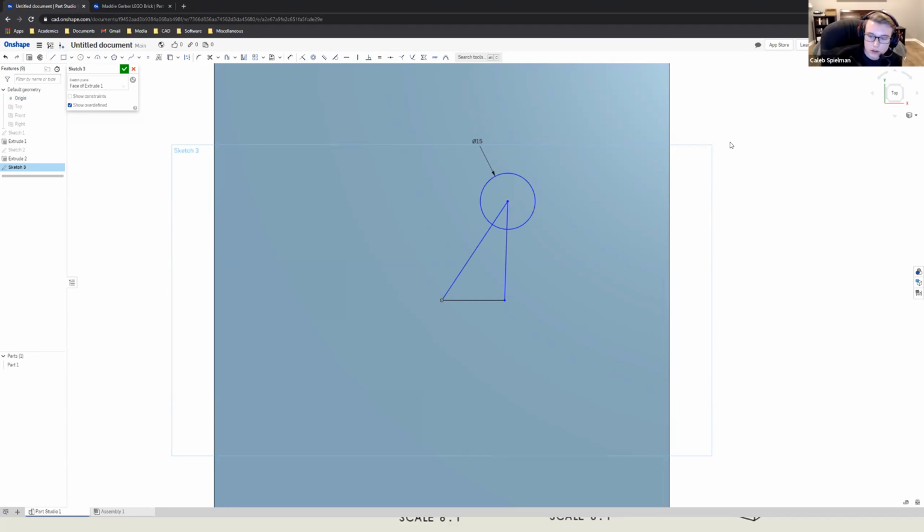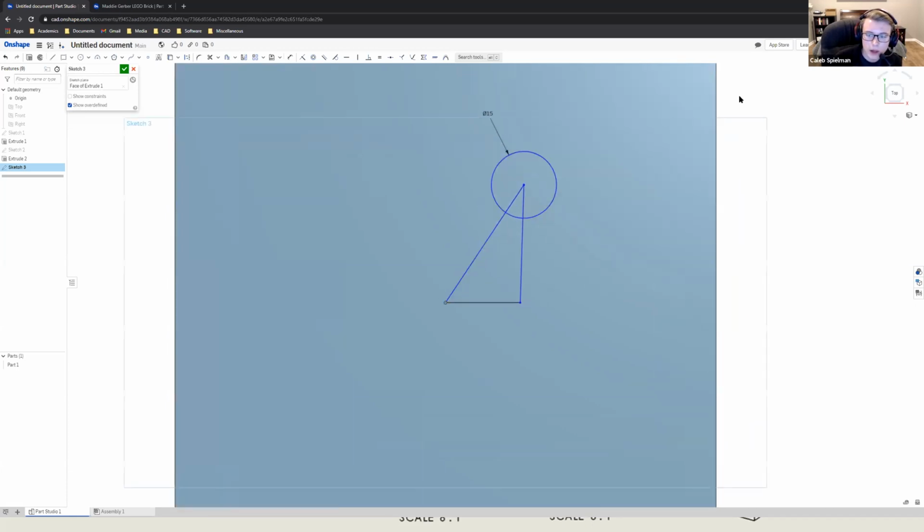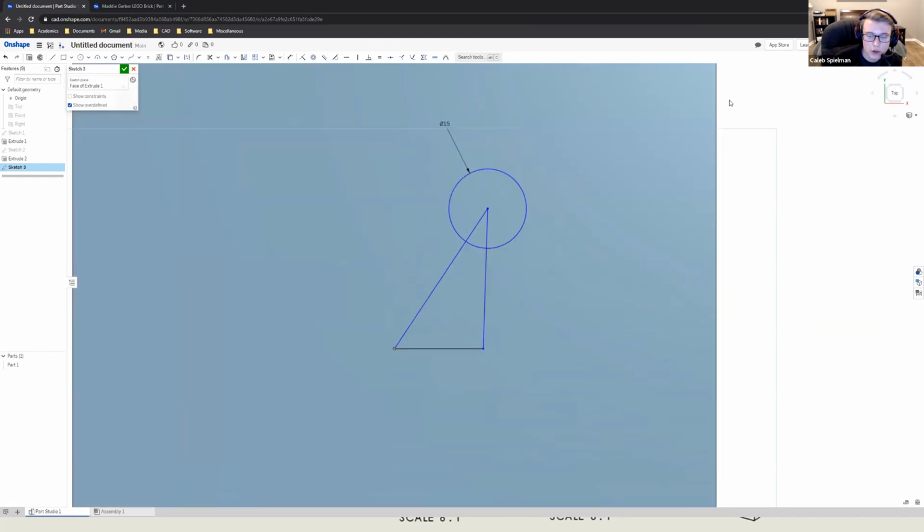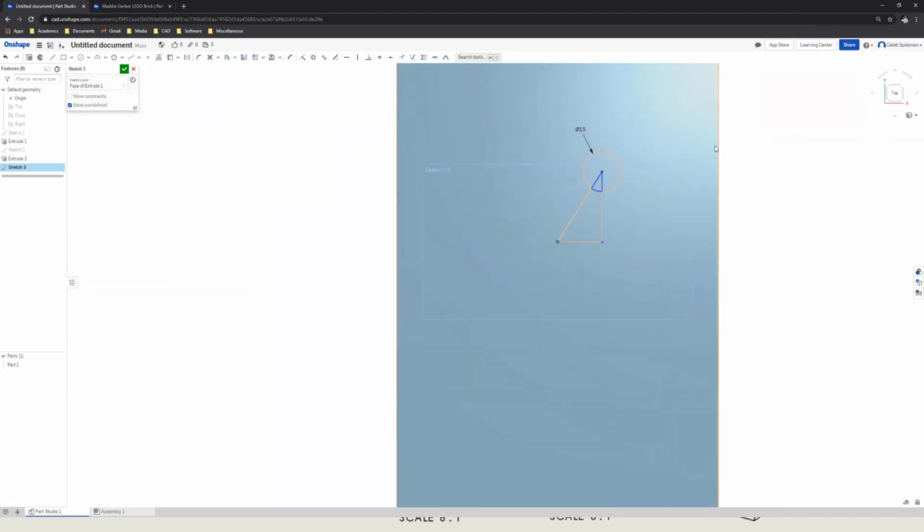All right, so in Onshape, it's a little strange. Not super different compared to other programs. Here to the right of the dimension tool, we have several relations that we can pick from. We have vertical, horizontal, perpendicular, and many things. So I could either choose perpendicular, since this line is already horizontal, or I could just click this vertical relation and then just tap on that line.